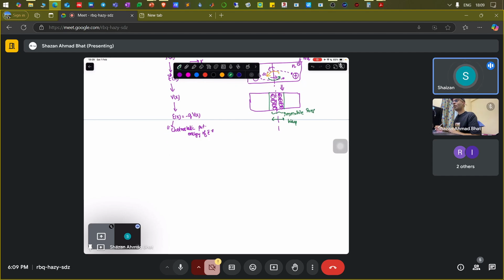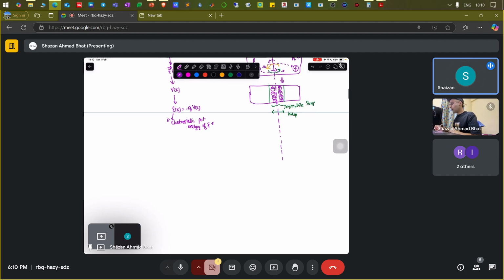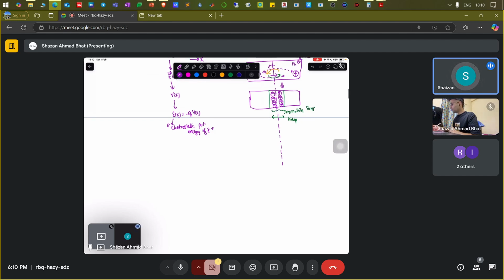And it gives rise to the formation of this space charge region, which is the depletion region, or transition region, or space charge region. It has been given different names in the literature. And now life becomes simpler. Why? Because if you know this charge, particularly this immobile charge, now you know whenever there's a charge, it sets up the electric field.